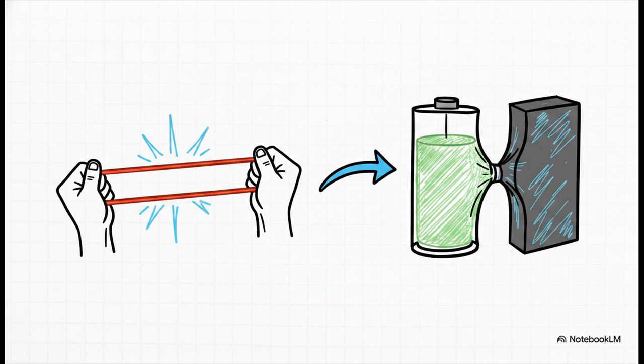This elegant little equation shows us strain energy, represented by U. It reveals that the energy stored is equal to the shear stress squared, divided by twice the modulus of rigidity, all multiplied by the volume of the material. In plain English, it means that larger objects, made of more flexible materials, put under higher stress, essentially act like massive invisible batteries. They're just storing kinetic energy, waiting for that force to be released.